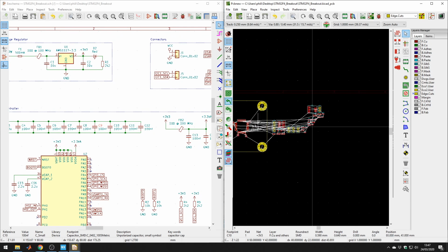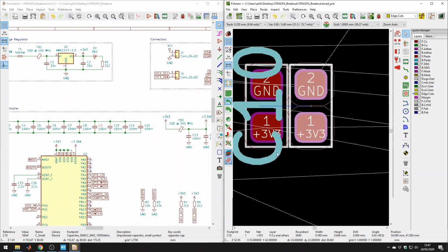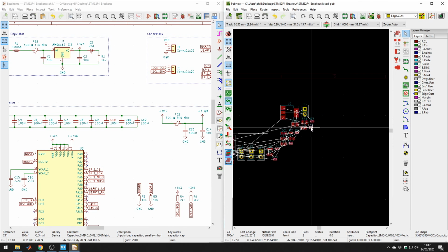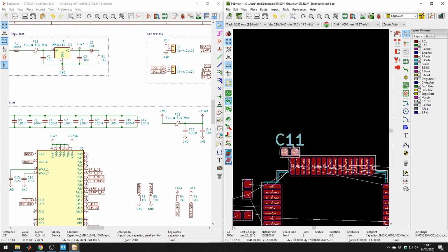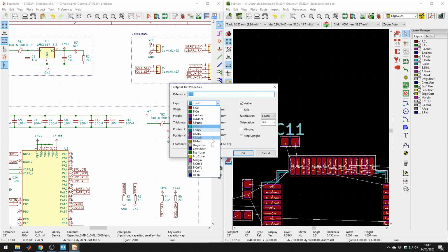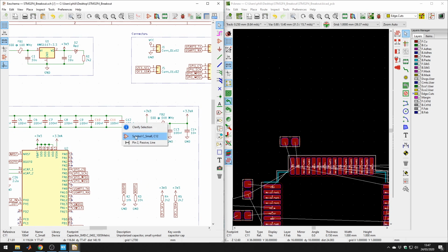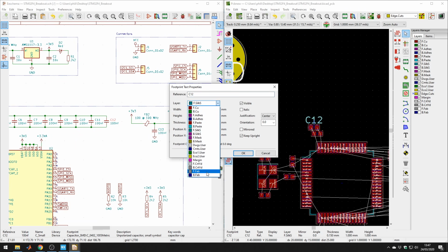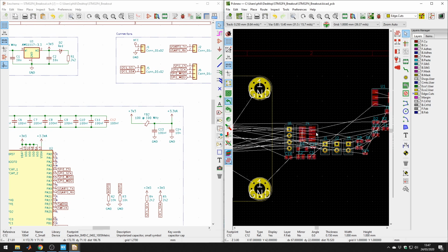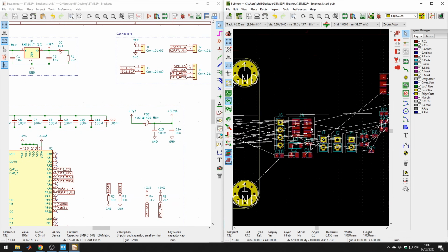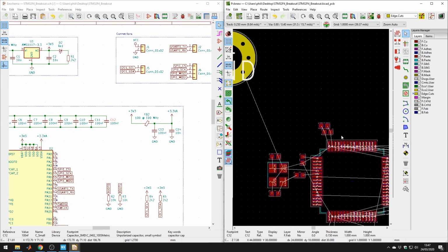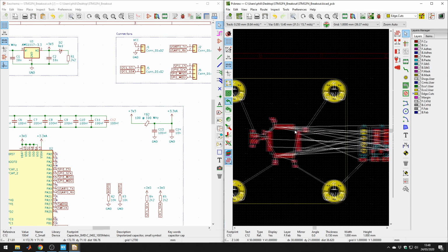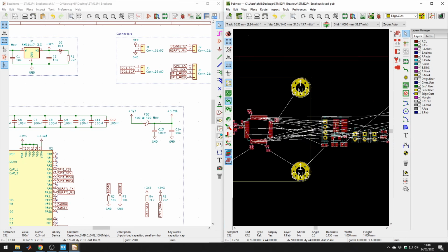C10, we're almost there. Amazing. Whoops. Fab. And the last 2 are going to go here. Remember, rough placement. It'll look a lot neater when we're done. But it's also a good idea because if you do a rough placement first, you can kind of gauge if things are going to fit or not. If you need to make the board bigger, if you need to rearrange components, instead of going in directly and fidgeting with the very small grid sizes and trying to get it nicely, things are bound to mess the component placement up. So just do kind of a general rough layout first.